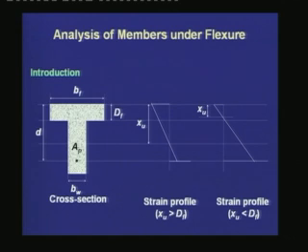In this sketch, we see a flange section where the flange in the top is under compression and BF denotes the breadth or the effective width of the flange, DF denotes the depth of the flange, and D denotes the depth of the CGS of the pre-stressing steel. BW is the breadth of the web.